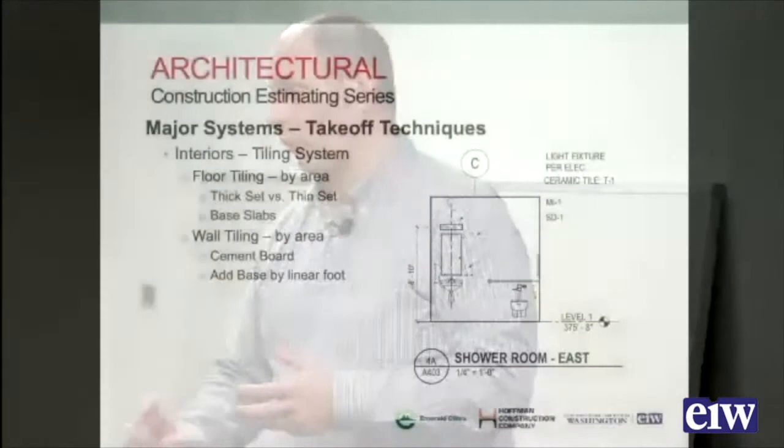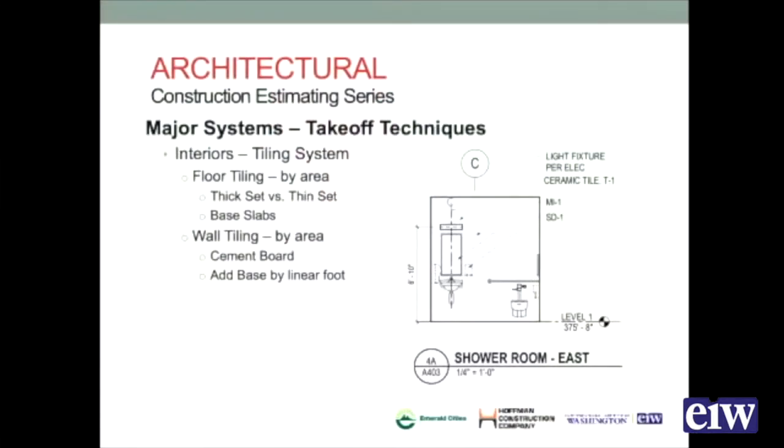It's going to be a much more labor intensive installation. You need to know whether there's a base slab. Some of these thicker tile or stone tile systems will actually have a slab underneath them that you need to pour in for support. Details will show all this, so you'll be able to understand if you need it or not.